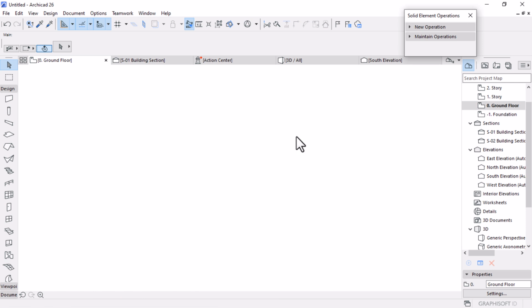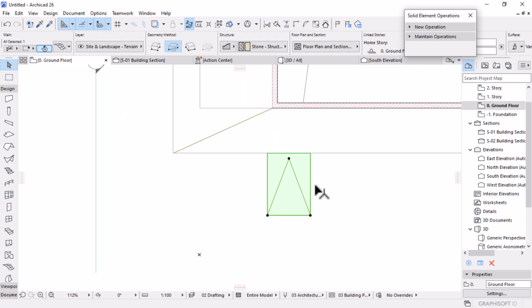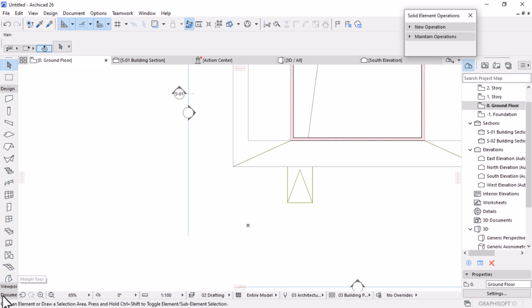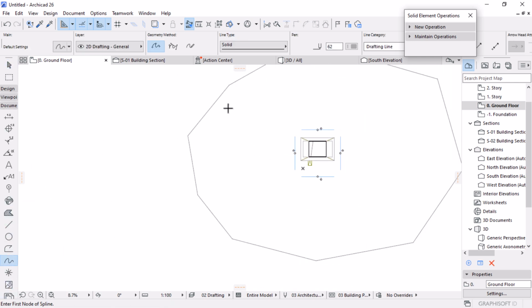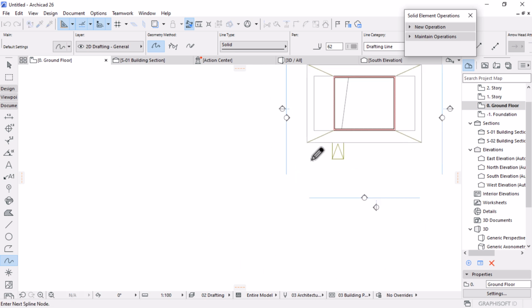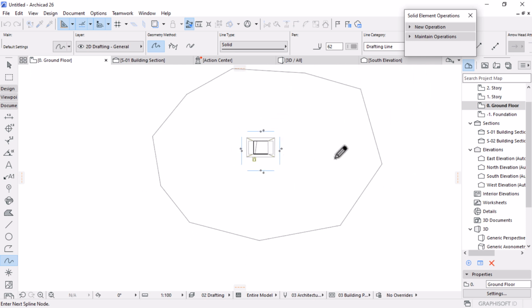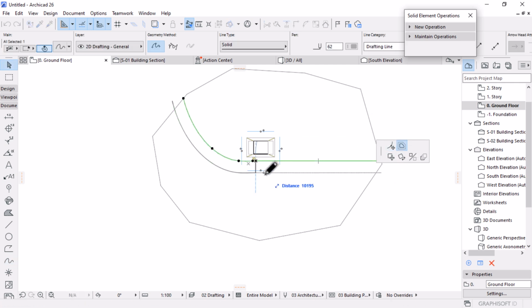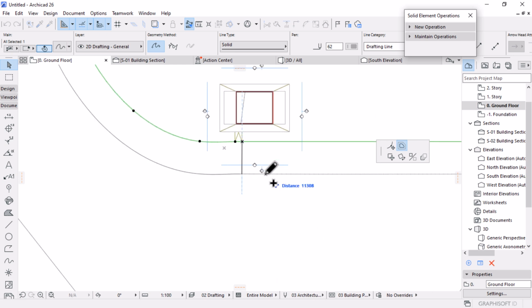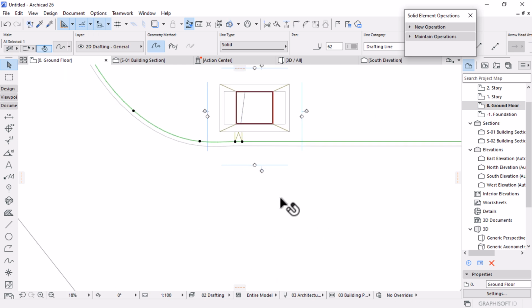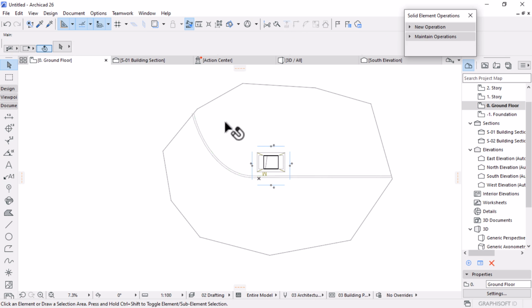Great. Okay, so let's do a path now that will service that ramp. So I'll come here under documents and pick the spline tool. I'll draw a line from all the way to there that will pass by this, going all the way to there. Select this path, offset, add a copy by control, and then make an offset of 1.5. That will be basically your path.